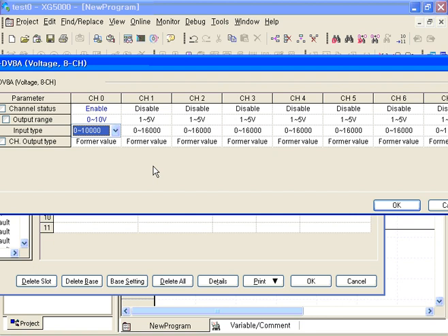What about analog output? You have to turn on the special output enable channel bits. After that, the output is made. Right? Kind of a trigger. You have to turn on the trigger bits for the output channel. For example, now I put 5,000 after enabling some trigger bits. Then 5 volts is applied, right? Now for the output channel there is 5 volts, correct?